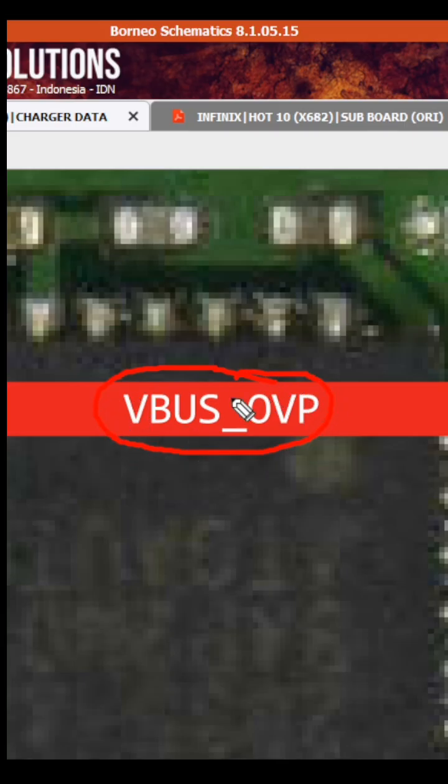It is the OVP that is now giving out this Vbus. This Vbus is no longer a Vbus that is coming from your charger. This signal is telling you that this Vbus is the one that the OVP has tested and told the IC that this guy is good, it's good for you to be used. So this guy is different from the OVP. That's why we have Vbus OVP. Okay, so I have told you in the last class that when a signal is passing through some process, the name will change. Hope you get it, guys.